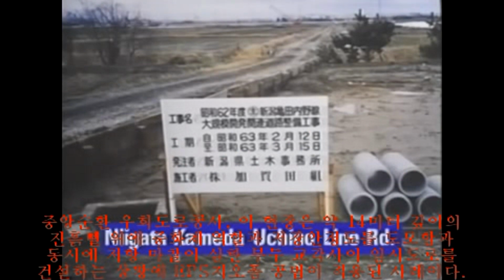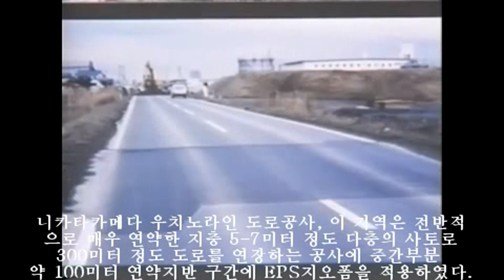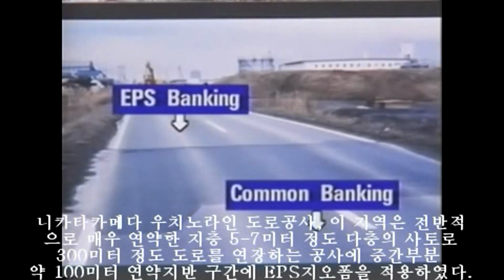This district has weak ground, consisting of a surface layer of 15 to 20 feet of viscous soil, humus, and a layer of sand. Of the 1,000 feet of road extension, 300 feet of the middle section used Geofoam lightweight fill as insurance against settlement. As you can see, a difference in grade developed between the EPS banking and the other bankings. Since this road was built for temporary use, it was removed after about 4 years.